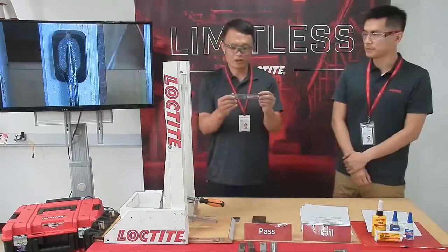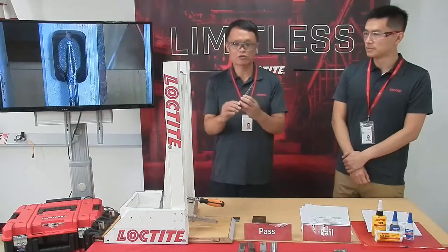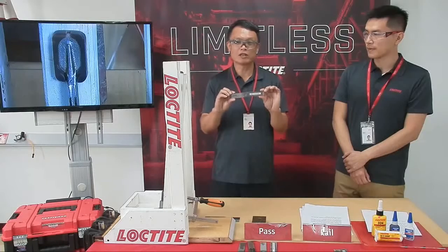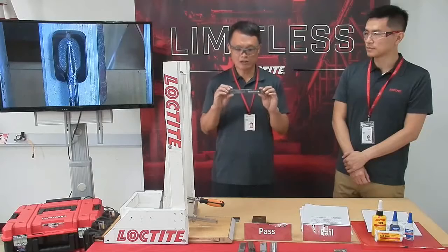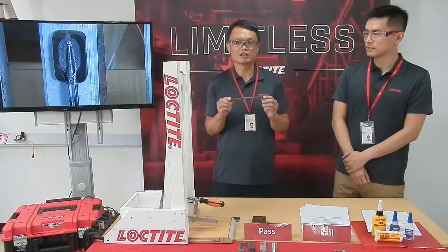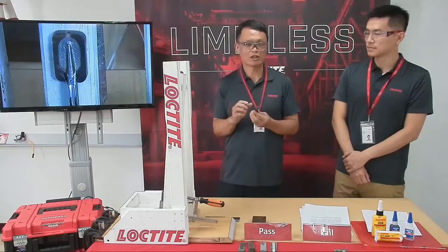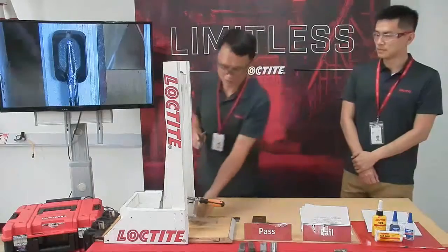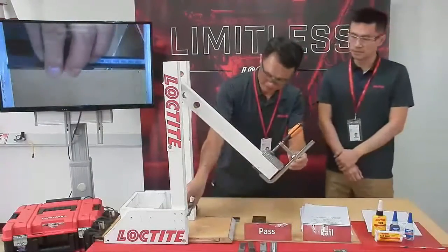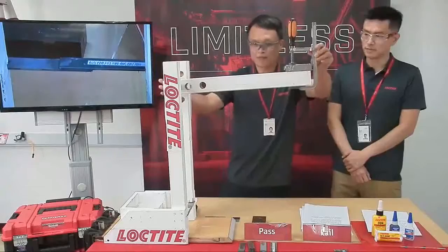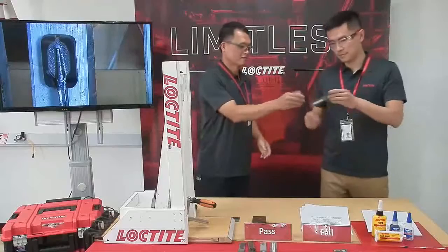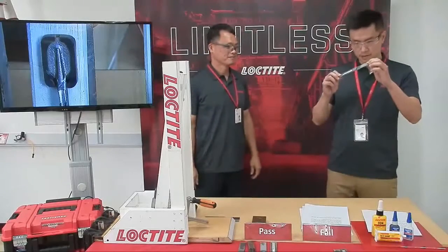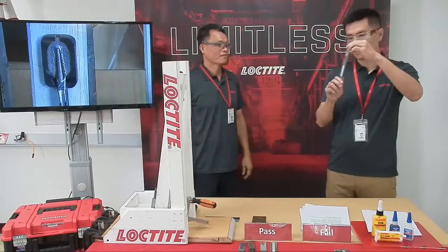Then we come to the last candidate. This is a structural epoxy. We have used this widely on composite materials for aviation, sports goods or sports bikes. Those kinds of products need very strong dynamic loading capacity. So we mount it onto the impact tester to see how it performs. Or it bounces back. It's perfect. Even a little bit better than structural acrylic.